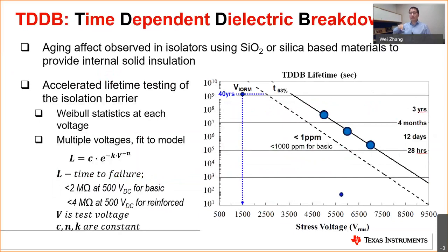And the next parameter I want to introduce is the time-dependent dielectric breakdown. As I mentioned before, only VDE has this parameter. And the newly released IEC standard for inductive and capacitive isolation also introduced TDDB. And what is TDDB? TDDB is accelerated lifetime aging, testing the lifetime of the capacitive isolation at a very